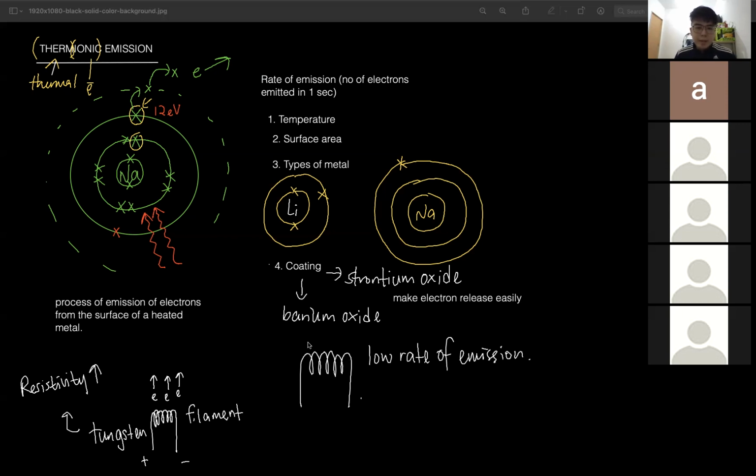They take the filament and then they put 1 extra metal piece on top of it. So that when the filament heats up, this filament heats up another metal here. And usually this metal is coated with barium and strontium oxide. Okay, they all work together like an integrated system. The filament, why we don't heat the metal directly? Why we don't heat this metal directly?